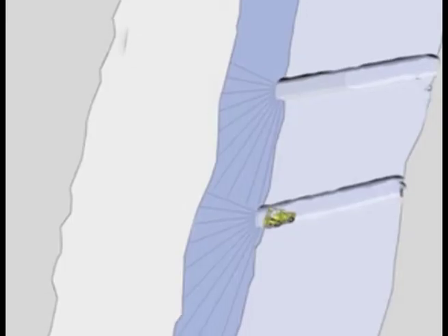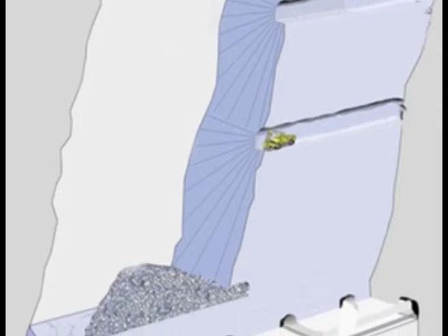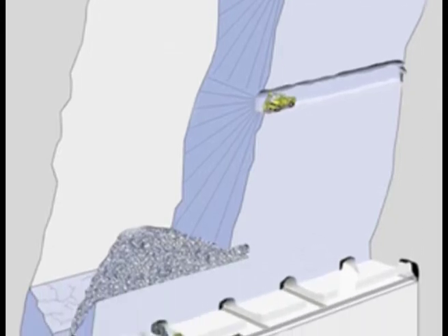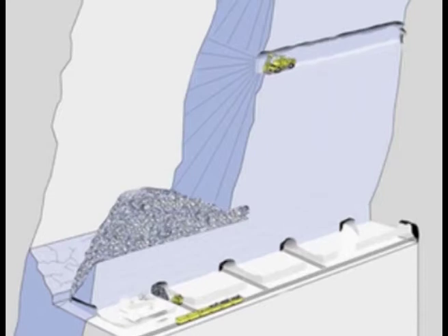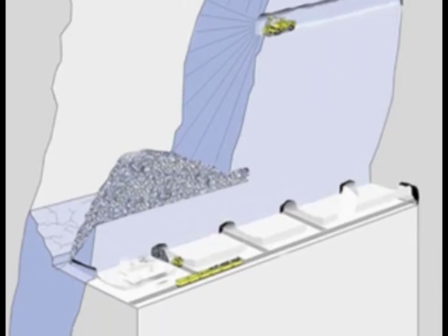Sublevel caving. Sublevel caving is applicable to mineral deposits with steep to moderate dip and large extension at depth. The ore must fracture into manageable blocks with blasting. The hanging wall will cave following the ore extraction, and the ground on the surface above the ore body will subside. It must be barricaded to prevent any individuals from entering the area.